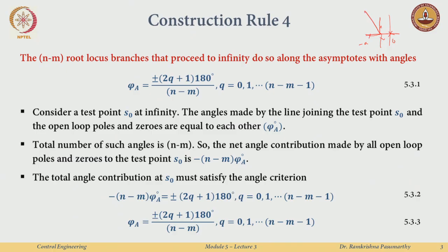Why don't they go something like this, or like this? Or why don't they, instead of going on a straight line, follow a lazy path and go a little more adventurous and go this way? Who decides how they go? In this example it was easier because it was just the solution of a second order, quadratic equation. So what if there are more poles that meet at this point? Can they go to infinity in the way they want, or is there something that decides that?